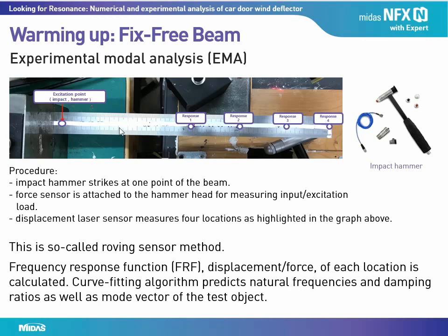For instance, we should also measure points along this section and more points everywhere. In general, we should try to avoid measuring a node of interest modes or resonance. For instance, this point, we should try to avoid it if the third bending mode is of interest.